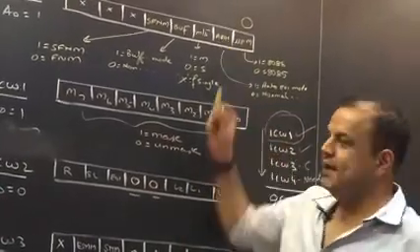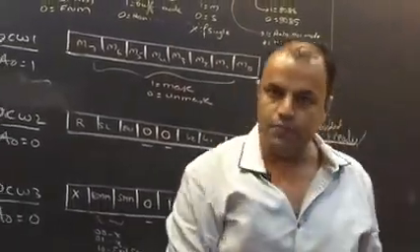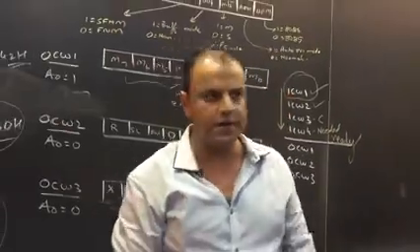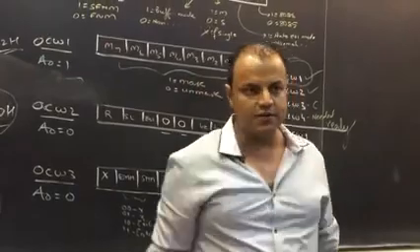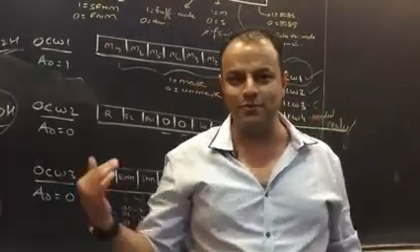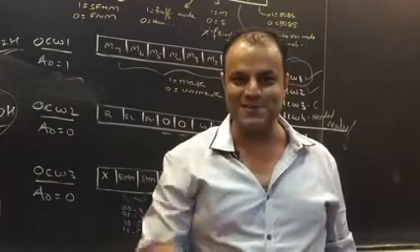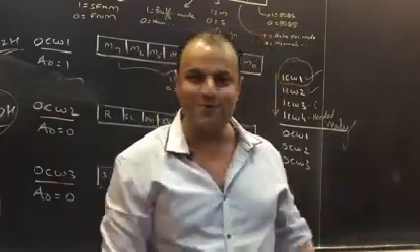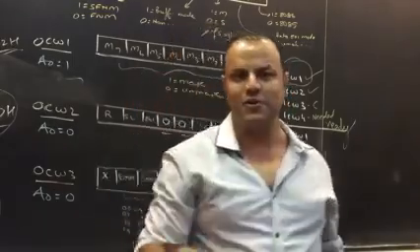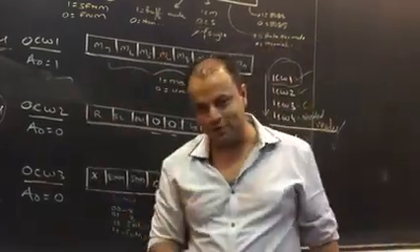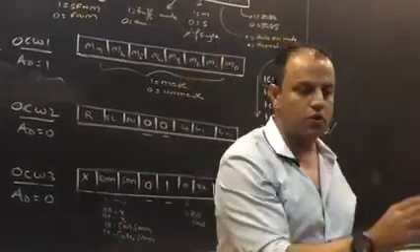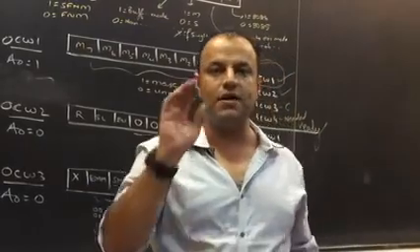Now, AEOI. I have made a video on operation modes of 8259. That is exactly the same whether it's 8085 or 8086, so I've kept the video common for both channels. Now if you see that video, you will see there are various modes: FNM, SFNM, rotating priority, auto rotation, specific rotation, special mask mode, poll mode, normal EOI mode, auto EOI mode, non-specific EOI and specific EOI commands. Do you remember that whole video? So in that I've taught you there is something called normal EOI mode where the programmer gives the EOI command, and there is something called auto EOI mode where we don't give an EOI command. EOI happens